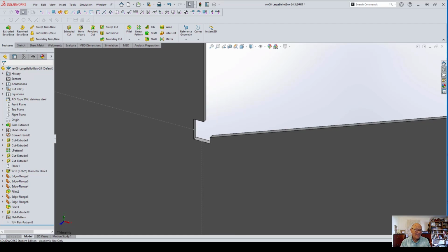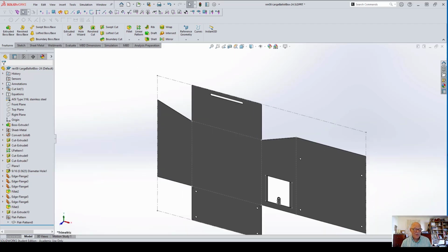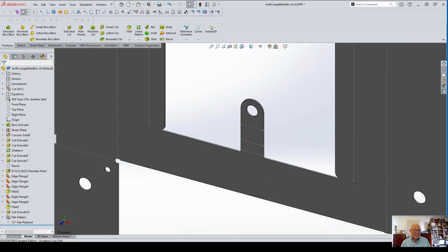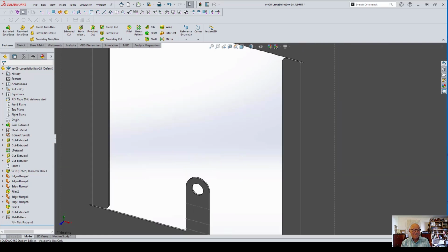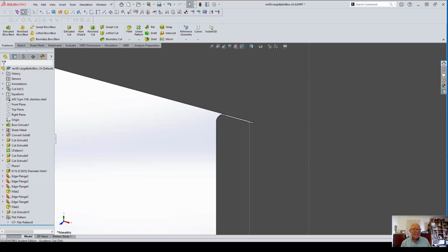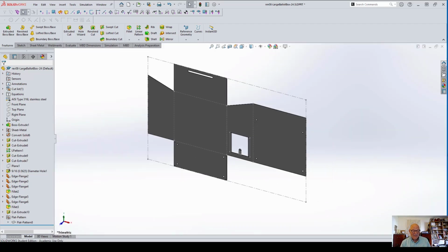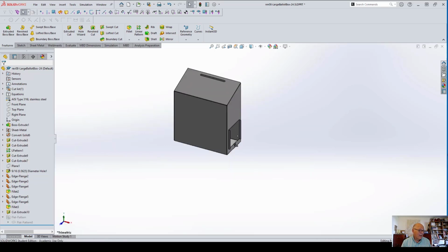Now you notice that all the corners have this little relief, because you can't just fold it with a square corner. It would bunch up and it wouldn't work very well. And then you have something down here that had to be folded multiple times. And then the tabs here had to be folded, but they also had to be cut. That's why the laser cutter was so nice, because they just fed this file to the laser cutter, it went around, and it had this thing all cut up. So what I'm going to do here is close that up. So here's how the process works with SolidWorks.